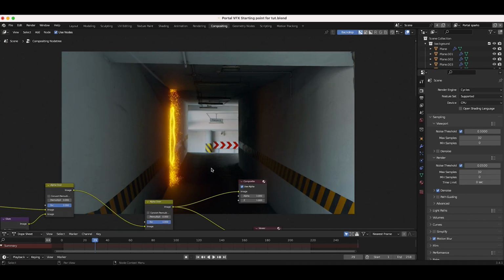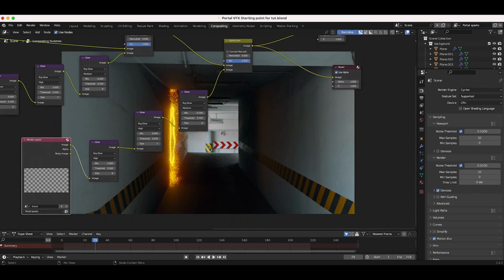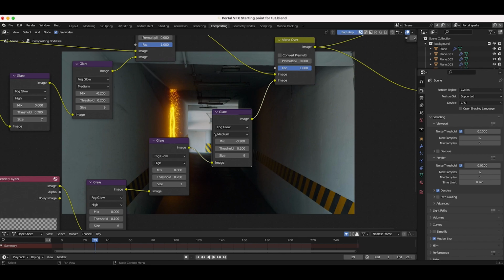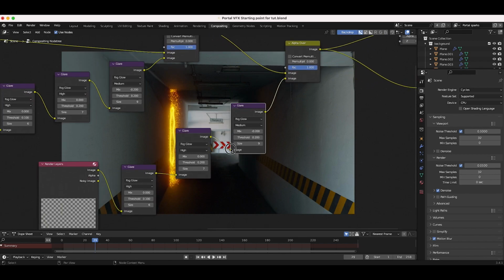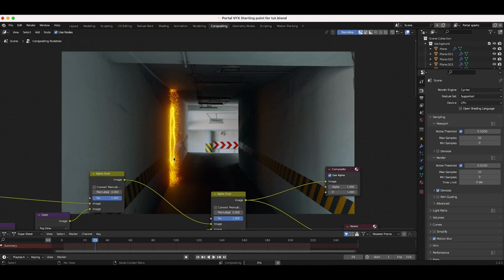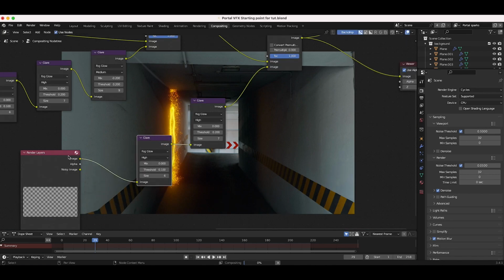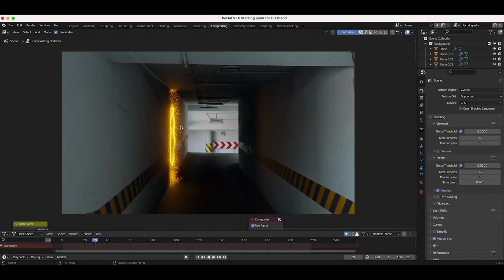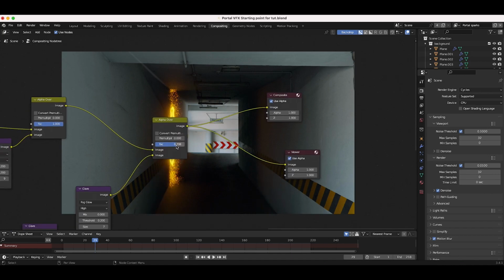All right, that's actually looking pretty cool here. Now, obviously we need to adjust a few things. I might not have the third glare node that I've duplicated here on the sparks view layer, so just remove that. But I'm actually liking the general look here. One thing I might do is just dial down the sparks a little bit. So maybe bring down the factor input to like 0.708. So now it's just a bit more subtle. I might split the difference, maybe do like 0.86.